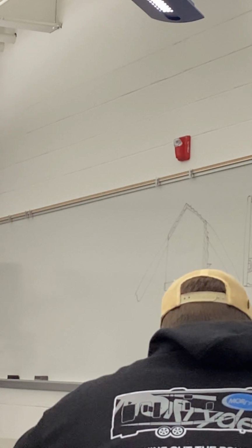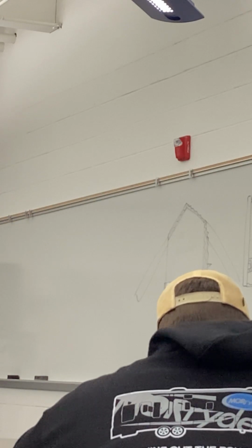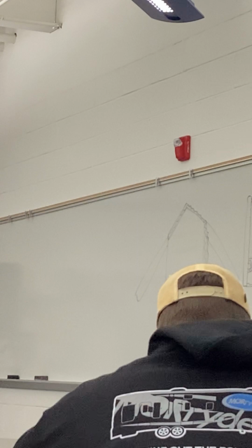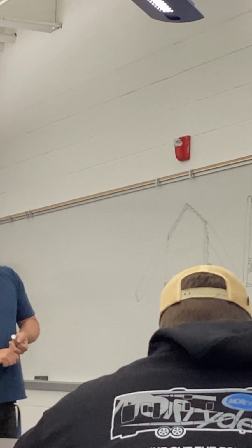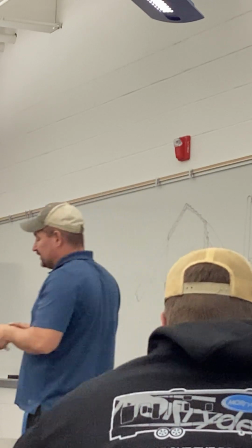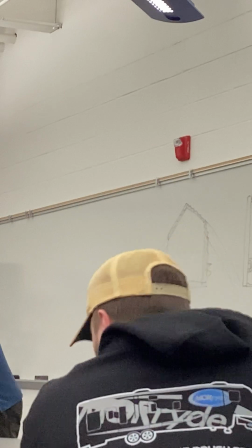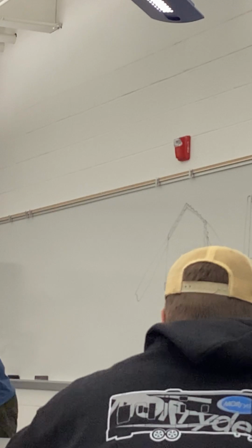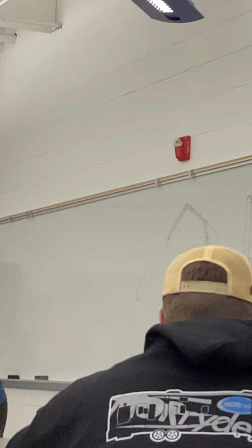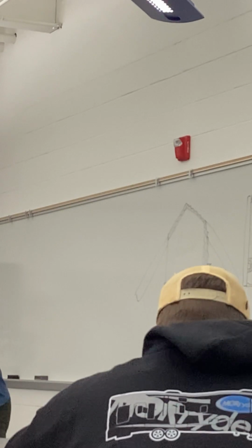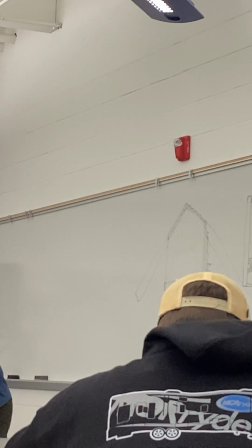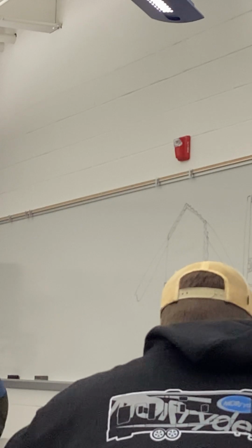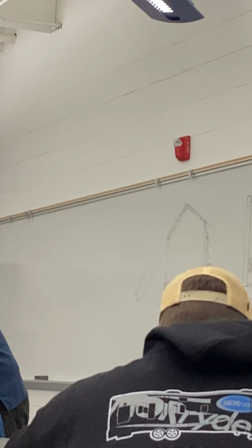Alright? So, what R value do we look at for walls? Typically R13, right? And it may say here, it may conflict with what I'm saying, but in our area, R24 is about peak. Anything above R24 they say is waste. There's too much insulation, you'll never pay for itself, or it's not cost effective because we don't have temperatures that require higher than R24.